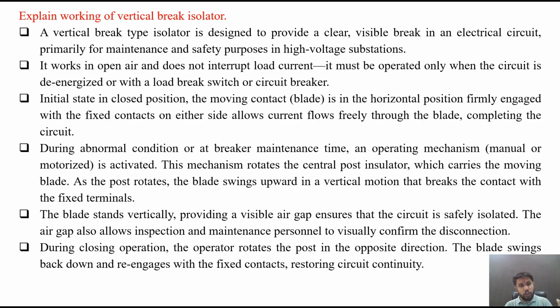But during abnormal condition or at breaker maintenance time, during that breaker maintenance, the breaker is operated, that is in open condition, so you can open the isolator. So an operating mechanism, manual or motorized, is activated. This mechanism rotates the central post insulator, which carries the moving blade.